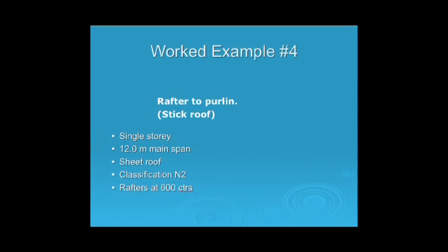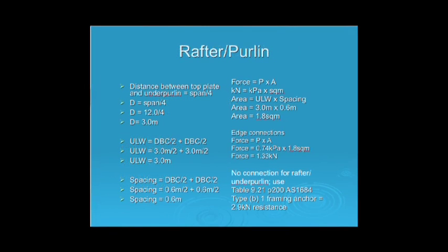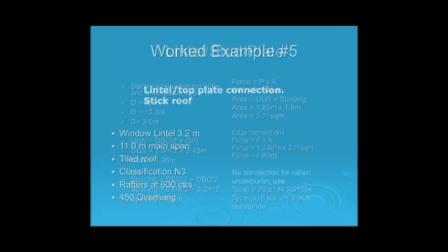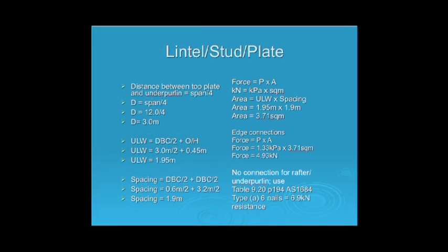The lintels, so there's a rafter under purlin connection that's been worked through, and you see that you can apply that here. And here's your lintel top plate connection, and this is how it actually applies here. And this is what we're going to do now. I'll just quickly do this one. This is a little bit tricky to draw this one, because if we're looking at it in plan view, we can't see, technically, the lintel connections underneath it.